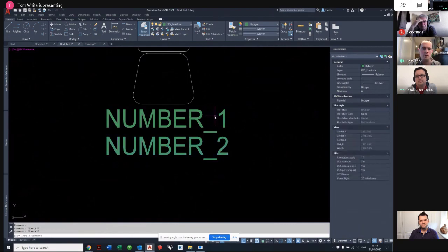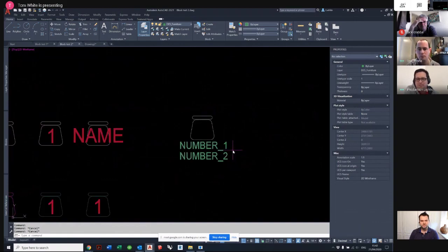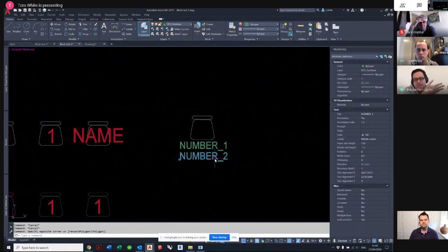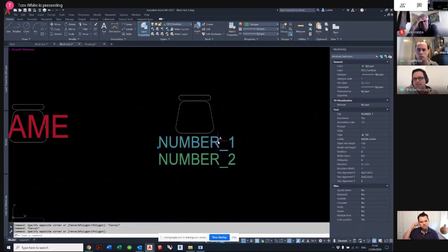I don't know if you do it a different way, Dom, but that's just a quick way that you can have 2 lines. It's absolutely the most obvious way, because as you said, you've done all the work. So you're just copying the information across, re-tagging it, and off you go, and then just resave as a block. And then, as you talked about earlier, from Dick's point of view, he can have quite large text information in the block, and then possibly buried quite small in it, other information about dimensions, which would then data extract out of the plan. It's all there, it's all been held, but it's not overpowering the plan.